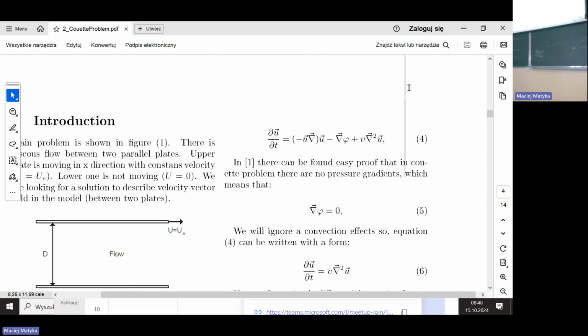It's wall shear stress. Okay, it's a kind of technical term. It's a force that is due to the viscosity effects that happen in the flow, which are described by this equation, but they happen at the wall. So it acts in this direction, but there is no normal force.